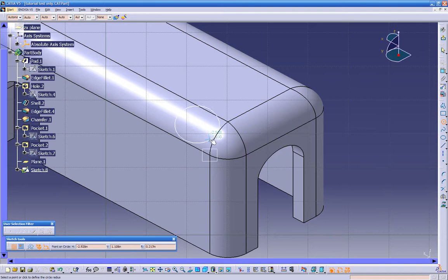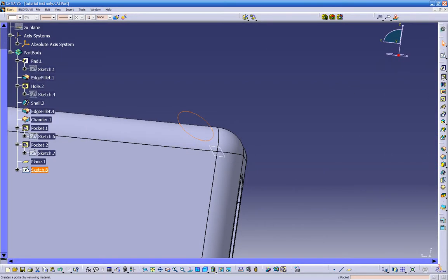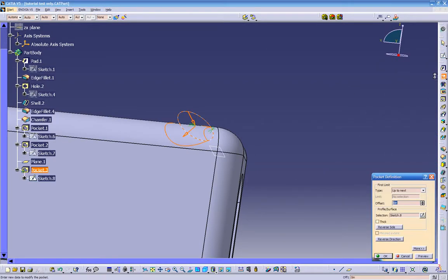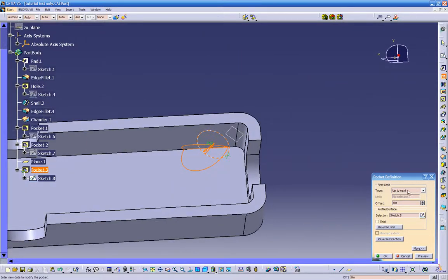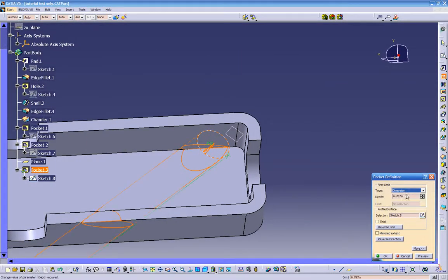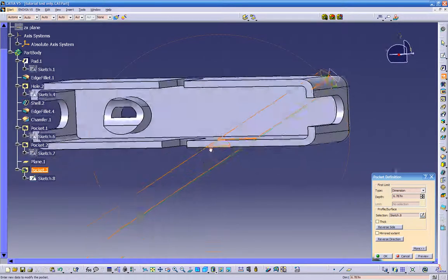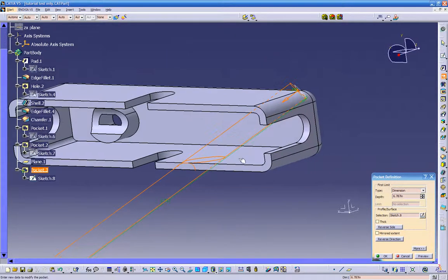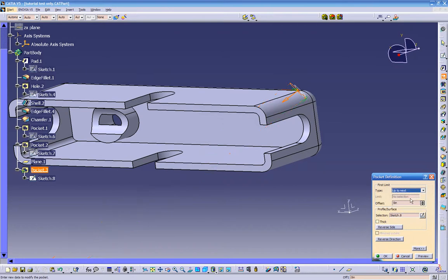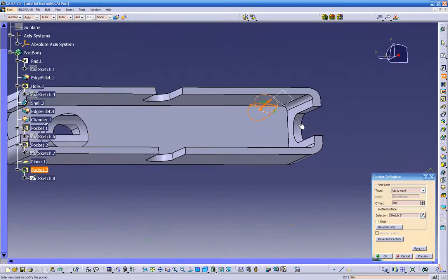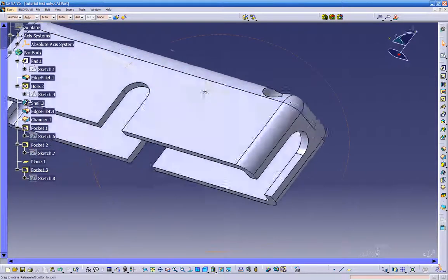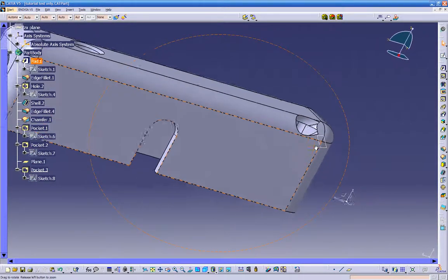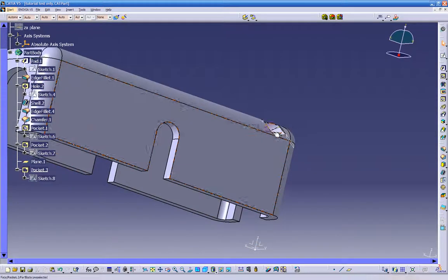our drawing shows. So click on arc, click OK, and then click on the pocket, and we can go up to next, or you can give it a dimension. It's going through the whole part. And if you want to go just to the up to next, it's just going to stop on the first surface where it's projected. So click OK, and there is our hole. What we can do, see, it didn't go through on the other side.